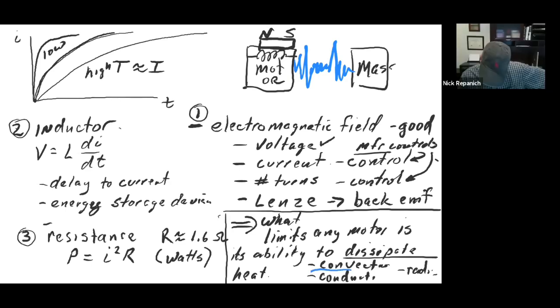Good answer. Nope, it's conduction. That's your key. Most motors are designed to pull the heat out from the face of the motor. There's a really nice flat face there that you would put up against another machine surface, and you're going to pull that heat out. They put fins on them and try other things convection related, but that just doesn't work nearly as well unless you start blowing fans on it. By the time you start blowing fans on it, you're using energy to move air around, and you're not gaining in the energy equation at that point.